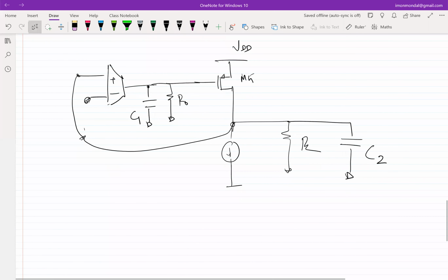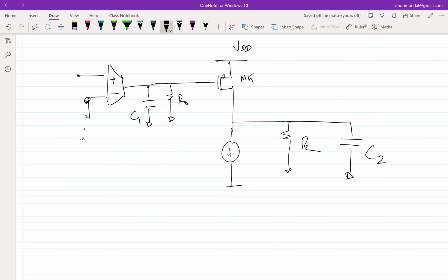So now what happens to the loop gain? What do you do again to figure out loop gain? Yeah, break the loop, ground it, apply V-test, and figure out V-return. C1 and C2 are the device capacitances I have clubbed together. We'll see how C1 and C2 relate to CGS and CGD, but let's assume that they are there because we cannot avoid them.